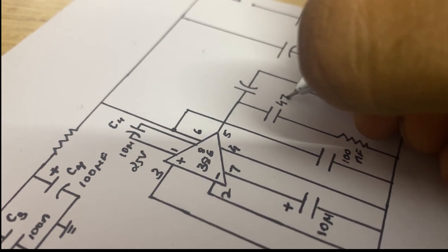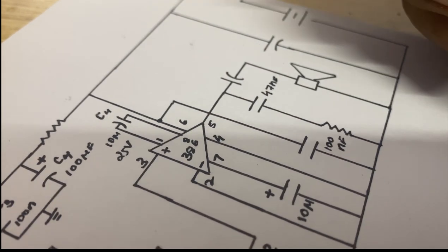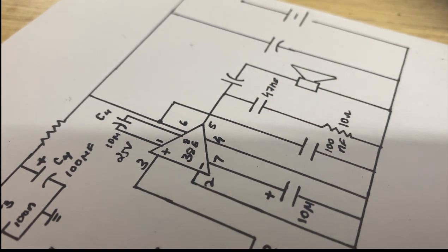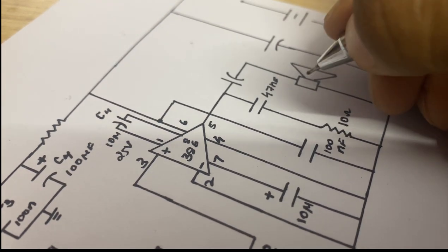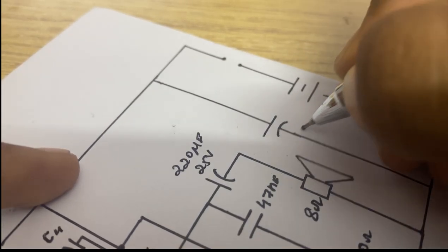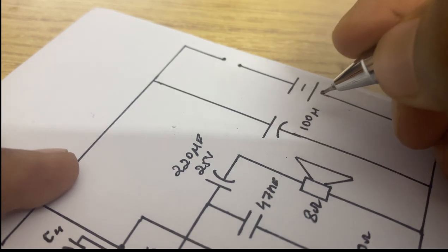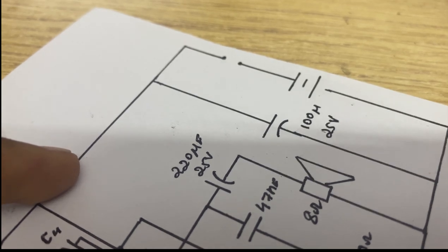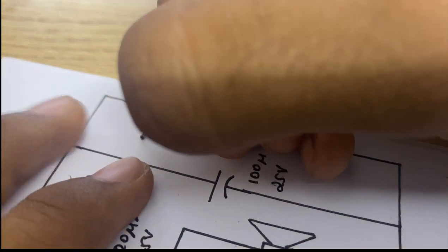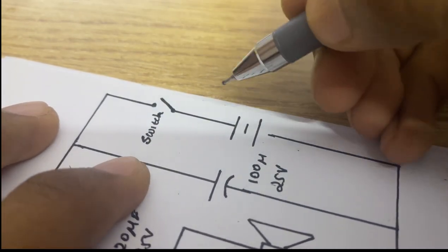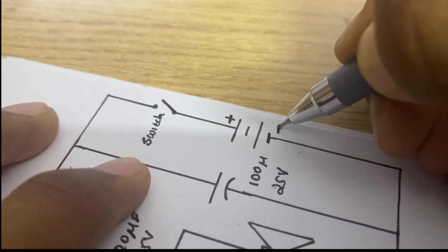Later on, when it comes to the next part of the circuit, the output of LM386 IC is fed to a speaker with a coupling capacitor of 220 nanofarad. We also used a 100 microfarad capacitor which acts as a filter to regulate the power supply without any fluctuations in the circuit. DC battery voltage of 6 volts to 9 volts can be given to the circuit. So in brief, this will be the complete circuit after the design.